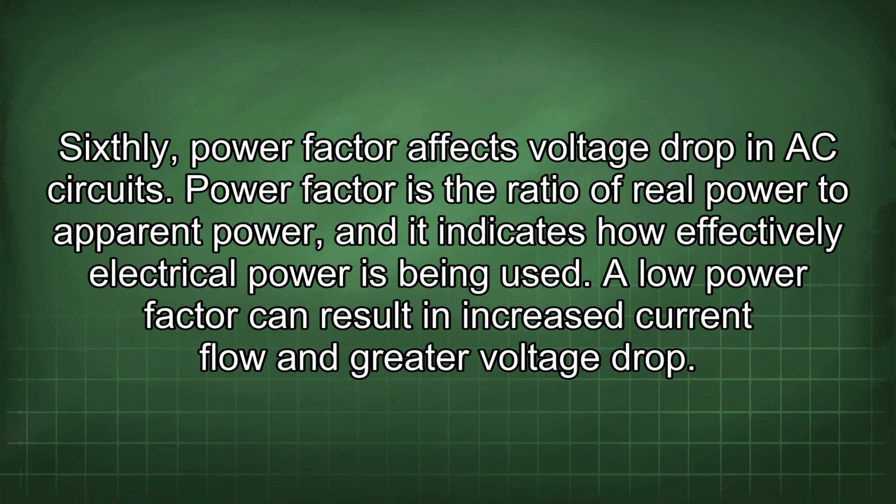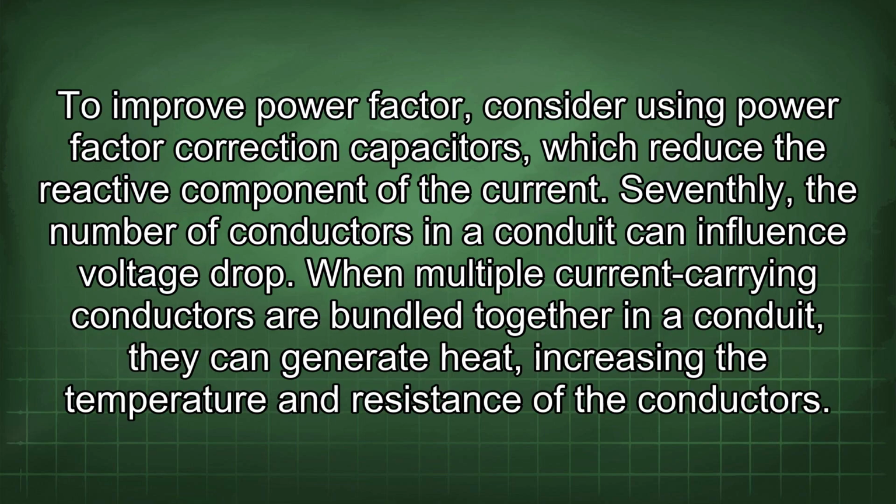Sixthly, power factor affects voltage drop in AC circuits. Power factor is the ratio of real power to apparent power, and it indicates how effectively electrical power is being used. A low power factor can result in increased current flow and greater voltage drop. To improve power factor, consider using power factor correction capacitors, which reduce the reactive component of the current.